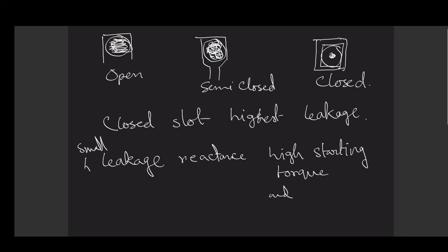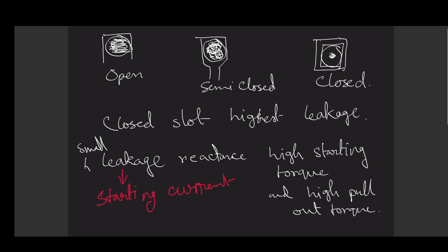and high pull out torque. However, the problem with this small leakage reactance is a dangerously high value of starting current. I am repeating to make it understandable that small leakage reactance implies high starting current.